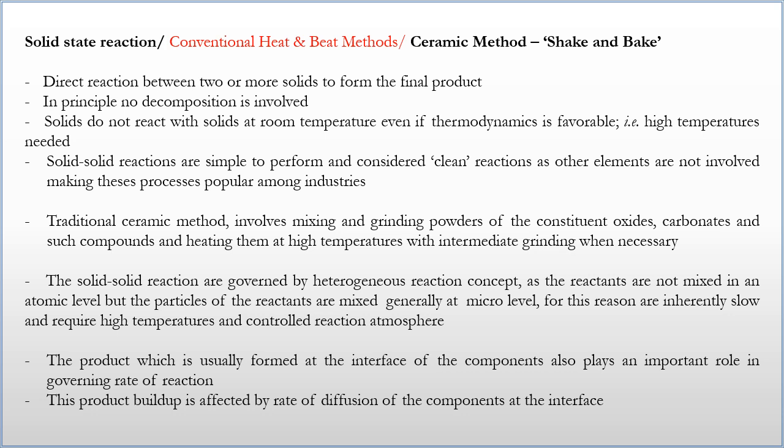Sometimes in a particular atmosphere the reactants are not stable, or the products are not stable at that elevated temperature, then also you have to control the reaction atmosphere, and you also have to control the rate of flow of the gas which you are using for maintaining that reaction atmosphere.